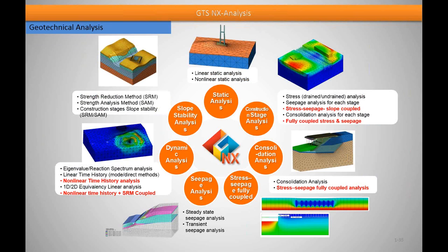Now talking about the GTS Nx capabilities, you can see that in the static analysis it has both linear static as well as non-linear static analysis. Also in the construction stage analysis, you can see two highlighted things, that is the stress seepage slope coupled analysis. Basically with MIDAS GTS Nx, you can now consider the simultaneous effect of the same. Let's suppose if the seepage is taking place, how it is affecting the stress simultaneously could be studied. So a very real ground simulation is possible, and so is true with the stress seepage fully coupled analysis.